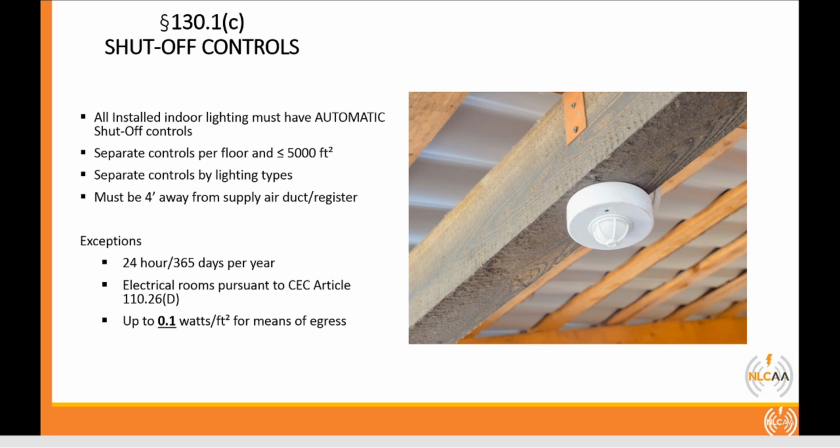Okay. All right. So if you're using occupant sensing devices, you must mount the sensor at least 4 feet away from a supply air duct register. And that's very important because it is a code requirement. You don't actually find it in the standards, the actual code standards. You'll find it in the test procedures for the certified acceptance test technicians that go out there and do the verification and acceptance testing. So very important.